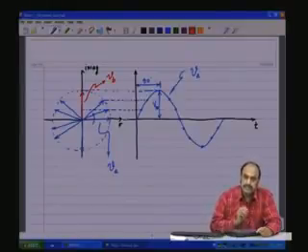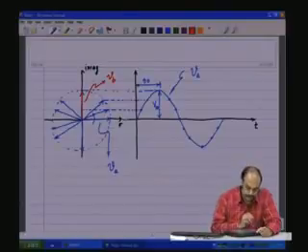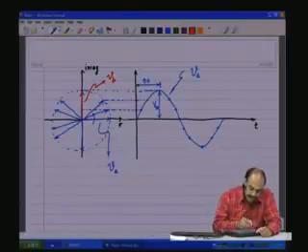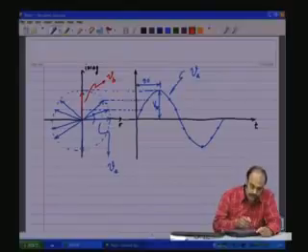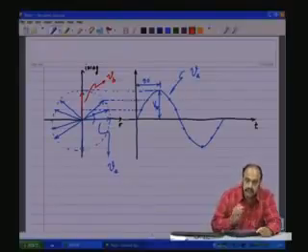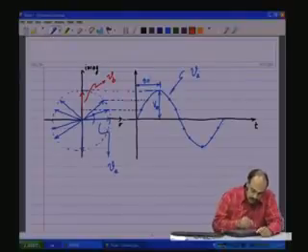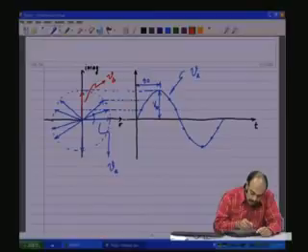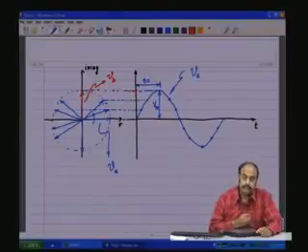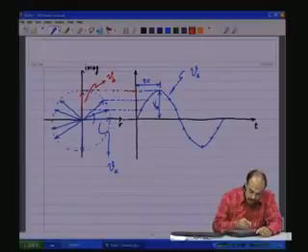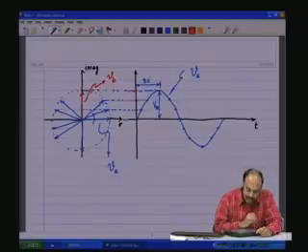This also has the same amplitude Vm, and this is also starting to rotate, and once the whole cycle is completed, one period is completed here. So, which means the red space vector on projecting will start from here at time 0, when the blue space vector is starting here.